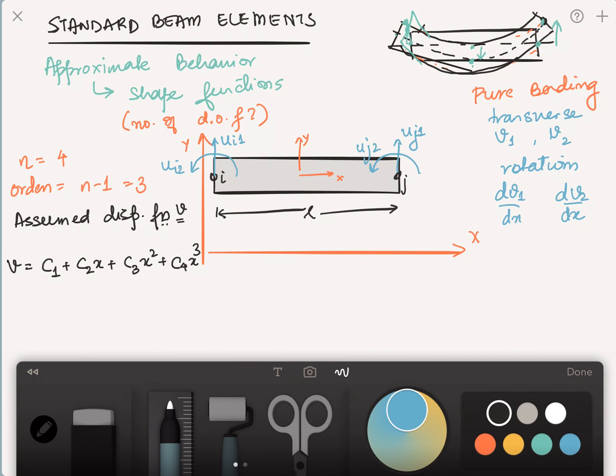Now of course this should be permissible, therefore it has to support all the boundary conditions, and it has to be C0 continuous. Now the shape function can be derived in a method very similar to the one shown in the previous videos and the previous weeks. We know that there are points i and j, and in the x coordinate we can mention those points as xi and xj.